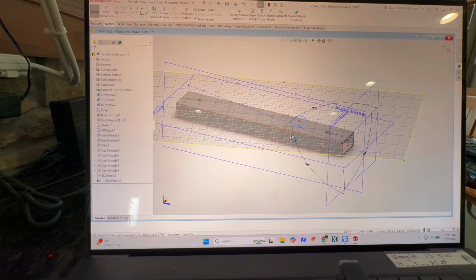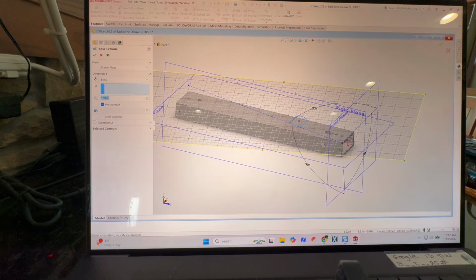But now I'm going to specify a true normal to this plane direction of travel, which we created down here. So let's try that. Feature extruded boss. And let's select the contour down here as this thing. Okay. And the direction right here is going to be this.